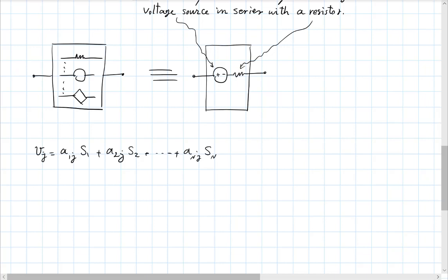And in fact, now taking this and thinking that if you're building a bigger circuit around this, so looking at this from the outside world, in this bigger circuit also this relationship will hold, then you will see that this linearity property will lead to the fact that what you see for that box from the outside will also be represented by a straight line, albeit with some shift, for which you need this voltage source. So this is really the root of it.